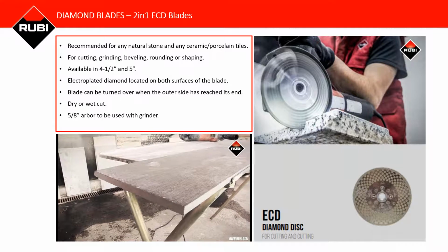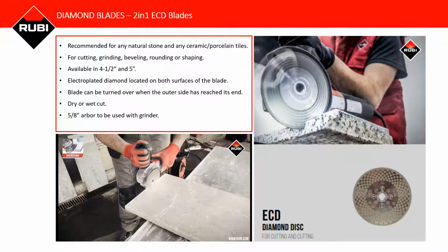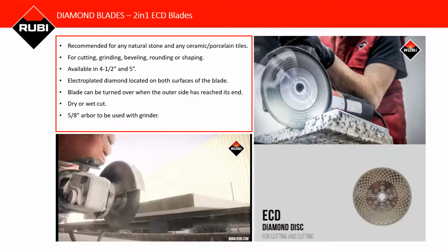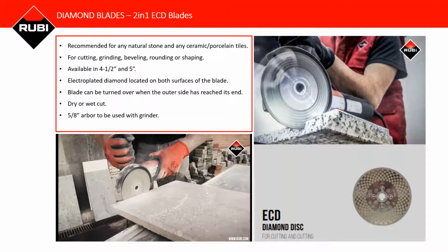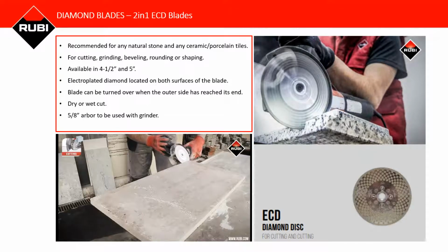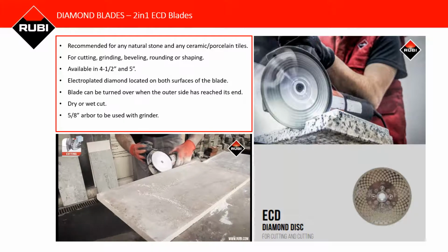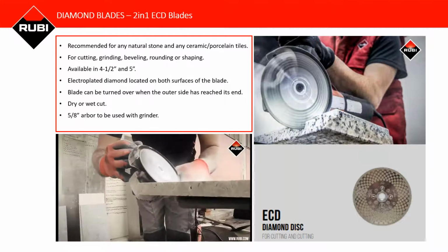Now, the reason why I recommend this blade is for our 45 miter cuts. The Viper is a very good blade. It's probably our best blade, but it's too thin to do a miter cut. So this is the blade I recommend to do the miters with the TC125, because it'll do the work and it'll fit on your TC125.